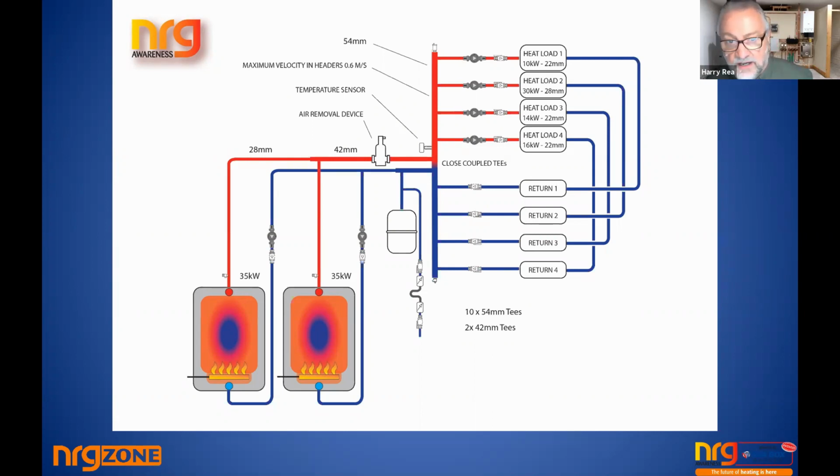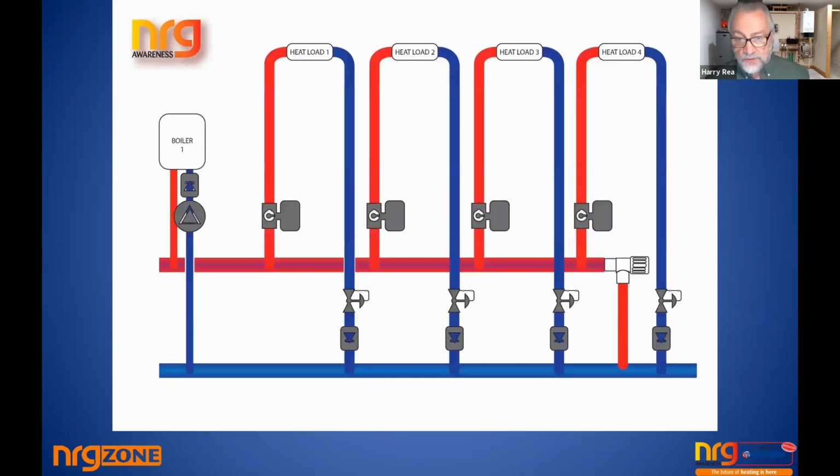If you look at the people who write the books on the subject, and if you certainly look at the brilliant videos from the likes of Caleffi and Taco and other companies like that, you'll find that this is absolute standard practice. Now there are different types of systems, and just keep in mind, we don't have to mention what size the boiler is over here, but you have to take into account if it's just a heat pump with 6 kilowatt output or 20 kilowatt output, it doesn't matter. The pipe size here must be an extraordinary size to carry the load. Within reason, the bigger the header you can have, the better the circulation, because now the pumps all have an equal chance of getting at the volume of water.